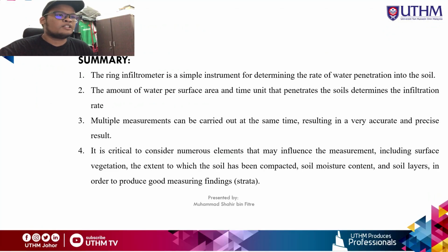Summary: the ring infiltrometer is a simple instrument for determining the rate of water penetration into the soil. The amount of water per surface area and time unit that penetrates the soil determines the infiltration rate. Multiple measurements can be carried out at the same time, resulting in very accurate and precise results. It is critical to consider numerous elements that may influence the measurement, including surface vegetation, the extent to which the soil has been compacted, soil moisture content, and soil layer, in order to produce good measuring findings.